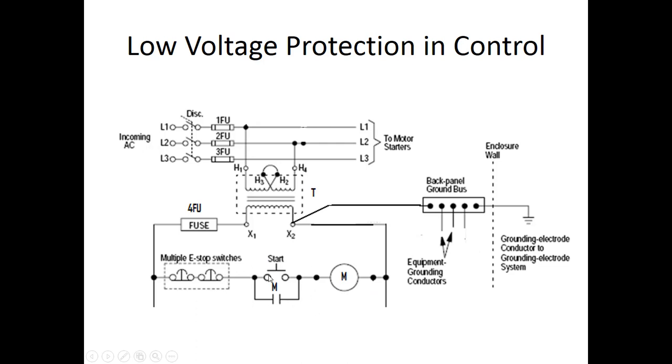So you have to physically hit the start to bring this contactor in here, and this is closed. This is a real contact and it will close. And remember, once that MCR comes on, it brings this voltage down here and high because there'll be a normally open contact there.